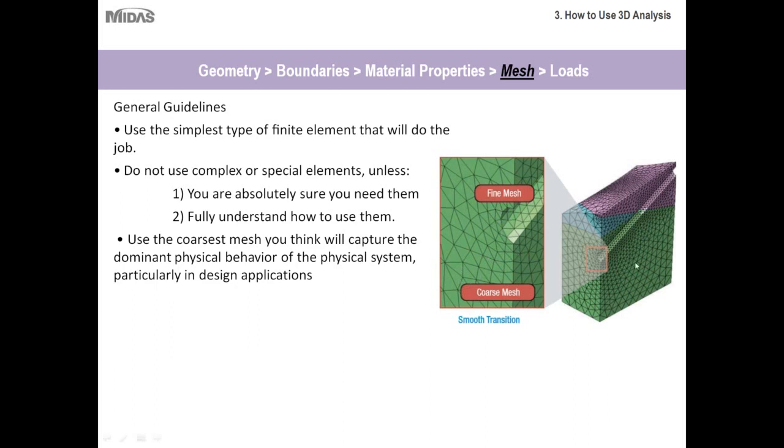As you can imagine, along the edges of this model, the displacements and the strains aren't really of interest to you. You have a better idea of what they'll be. Whereas along the lining of the tunnel and along the opening, that's the area of most interest to you. That's where all the changes, the failures, etc. are happening. So you want the mesh to be finer there, because the more finite elements you have, the more results you'll get, and you always want more results for these areas.